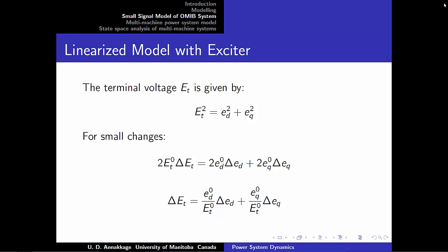The amount of voltage applied to the field winding is determined by the error between the measured and the desired terminal voltage. By increasing the field voltage, you can increase the terminal voltage, and by decreasing, you can decrease the terminal voltage.